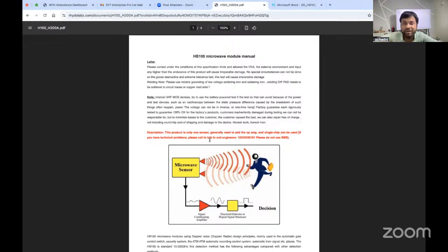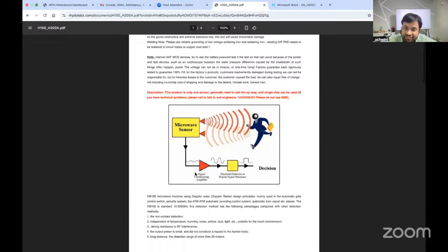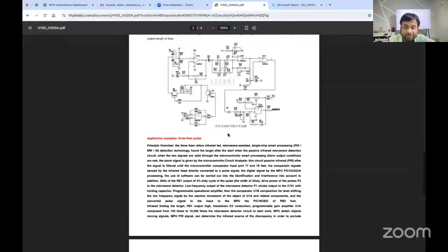So let's work on that. This microwave radar will send and receive microwave signals, and when a vehicle or a person comes at very fast speed in front of or even beside the radar, the Doppler effect happens. The signal compression and decompression occurs, and it measures the speed using that, by applying the formula.